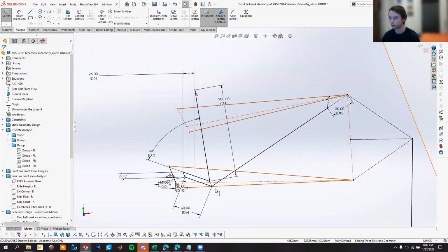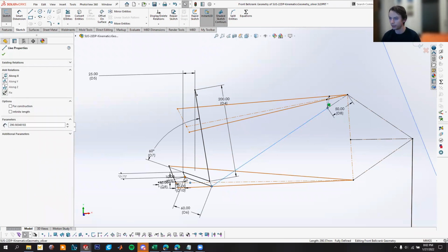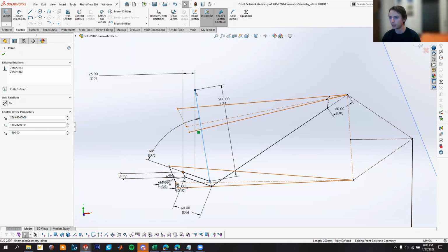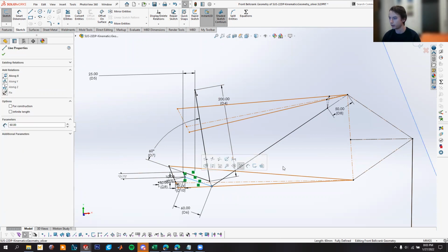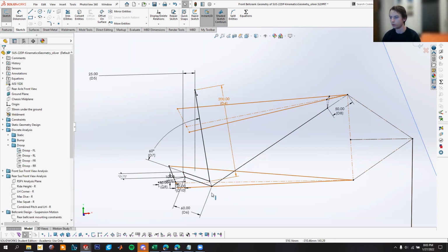And that changes throughout the suspension motion because the perpendicular distance between the pull rod and the pivot axis, which is this point here, and the perpendicular distance between the spring and damper and the same axis change as this component, modeled by these three lines, rotates in space.